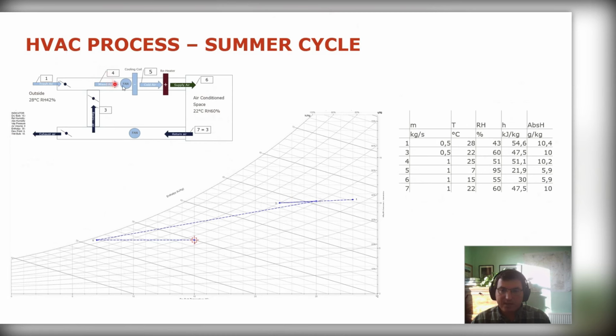Then that mixed air is going to go. Now, when it goes through the fan, by the way, technically, that would add some heat because of the inefficiencies of the fan. So I could show that as a sensible heating, but it's quite a small amount. So for simplicity on this graph, I'm ignoring it. But if you wanted to be really accurate, you could add an extra stage where the fan adds a little bit of sensible heating. So no moisture added, but just an increase in temperature. If you want, you could show that, but I'm going to skip that bit.